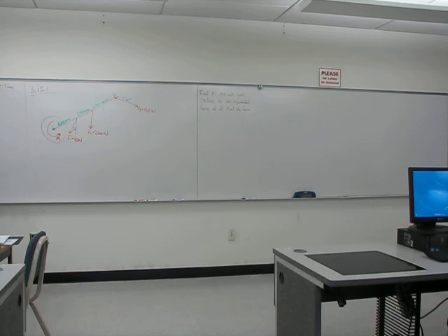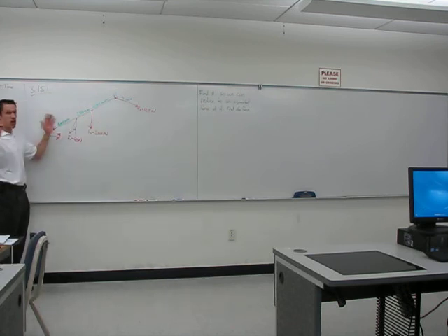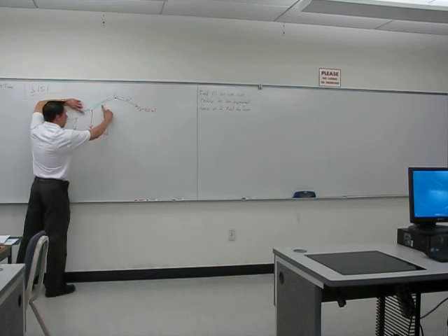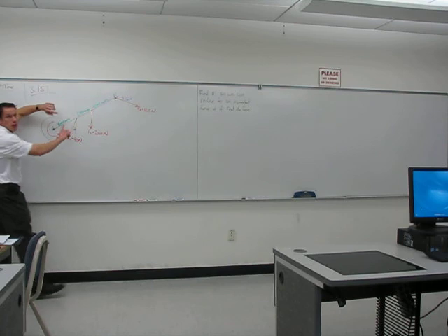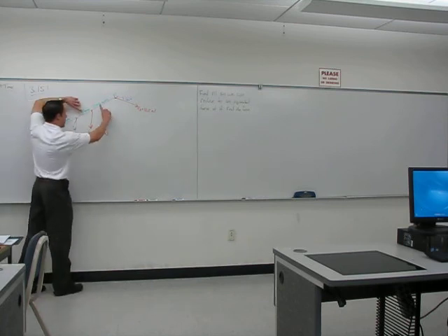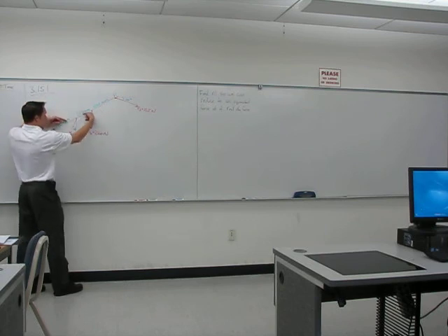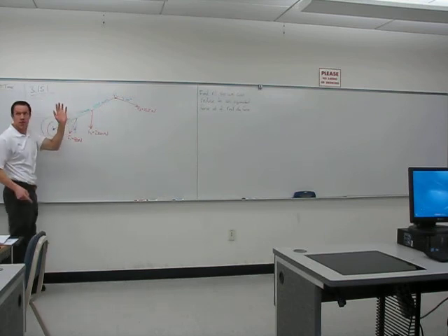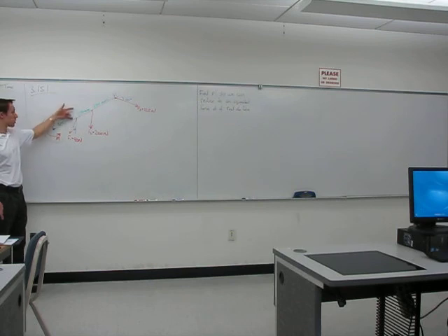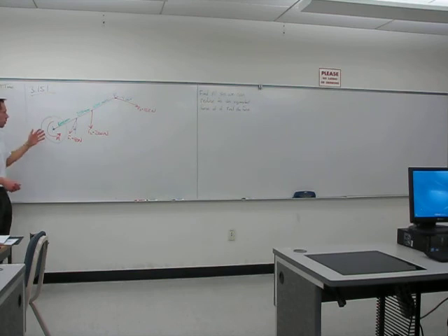So you might think about there really being 5 forces being applied: F1, F2, F3, and then somewhere on this rigid body, maybe it's here and maybe it's here, there's a force couple that has the moment vector that we have here, M. Remember that force couple, whether it's applied here and here, or here and here, as long as we have 2 forces of equal magnitude, opposite direction, if we do F times D for the magnitude of one of those forces and D the perpendicular distance between their 2 lines of action, no matter which point we were to find the moment of that force couple about, we would always get that same result.